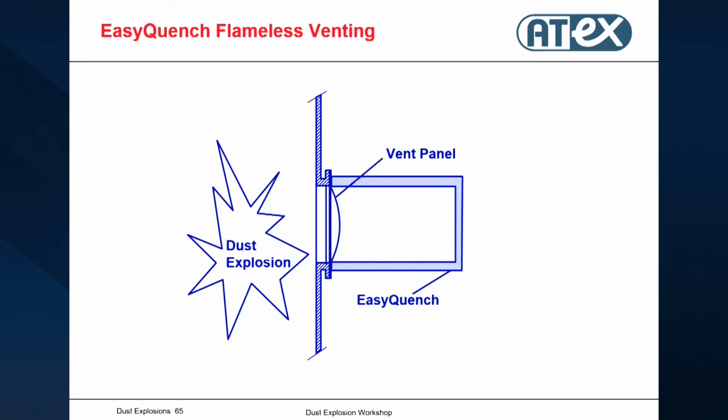And in certain applications, if you have relatively small volumes somewhere in the factory, then this is a very efficient way of doing explosion venting in buildings. Free explosion venting always has to go to the outside. Here you could have small volumes that you vent into the building without all the additional things that you might need. And you probably also know, if you have equipment that needs to be channeled to the outside with a duct, then it has a very negative effect on your venting process. This has a much lesser effect.